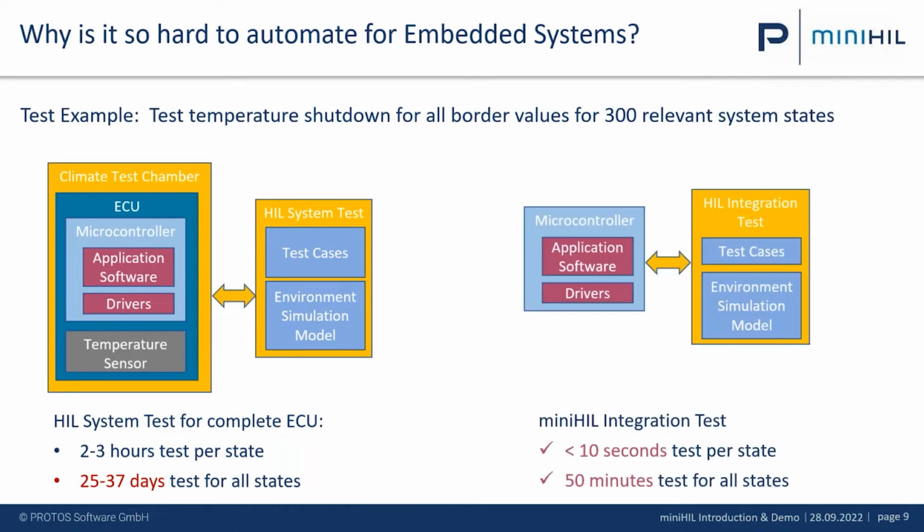So what we did is we took out the microcontroller and just tested the microcontroller with the drivers, with the application software. So the complete software as it is, but we simulate all the IOs at the pins on signal level.